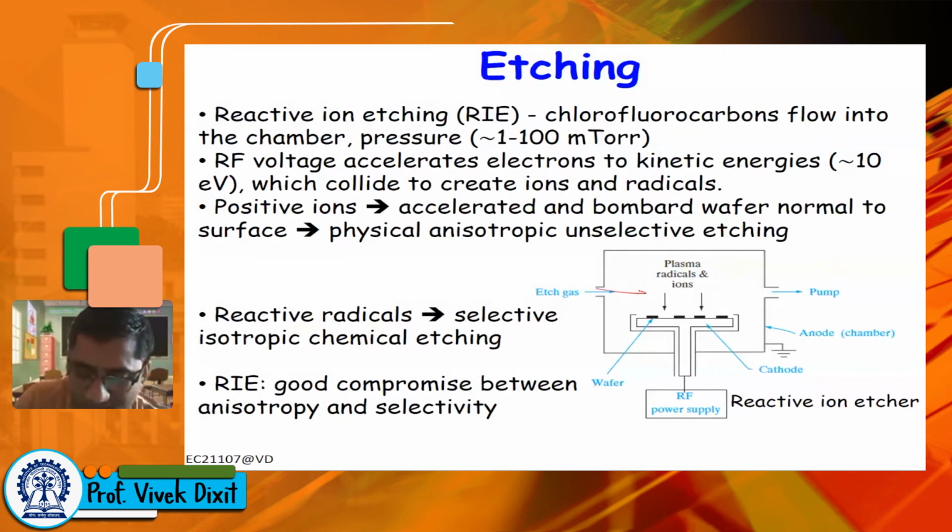They flow into this chamber, and some potential is applied here, an RF power supply. So this is basically anode, and this is cathode, a negative terminal, positive terminal, and its surface area is less. So what will happen? A plasma sheath will form here. So plasma is conducting, but inside this sheath it is not, it's hindering the movement of carriers, right? Movement of electrons and ions. So in case of plasma, electrons and ions are the carriers.